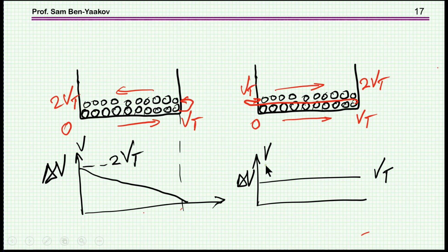On the other hand, if you do the following, if after finishing one layer you go with the wire all the way here and start winding again, then the voltage between the layers will always be the voltage of one drop of one layer. Now, since energy is voltage squared, having a large difference here will bring about more energy stored, or a larger equivalent capacitance.